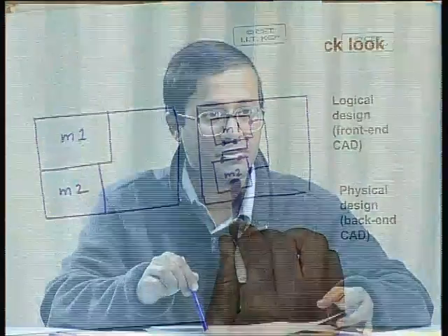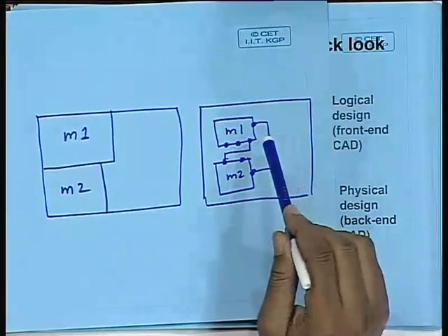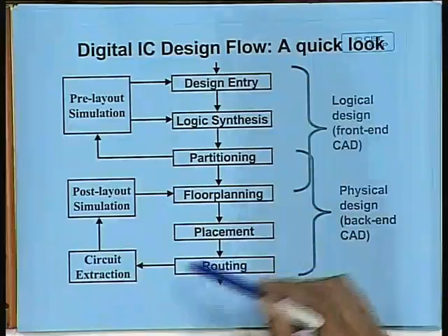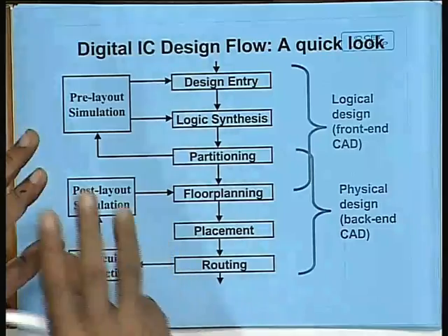Okay. So the routing will be done after placement. These interconnects will be done after the placement is done. Routing will also give you all the details of which layers are connected. Typically, when you are connecting modules at a high level, you try to keep most of the interconnections at the metal layers, but for some connections at shorter distances, you may also use other layers.